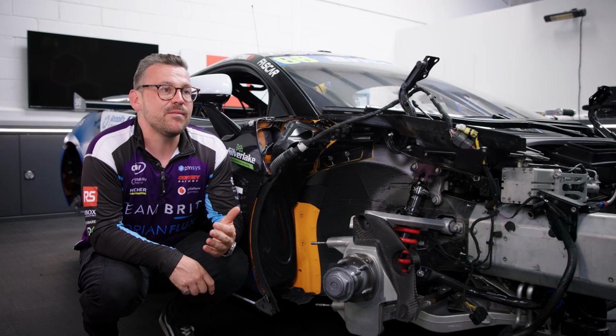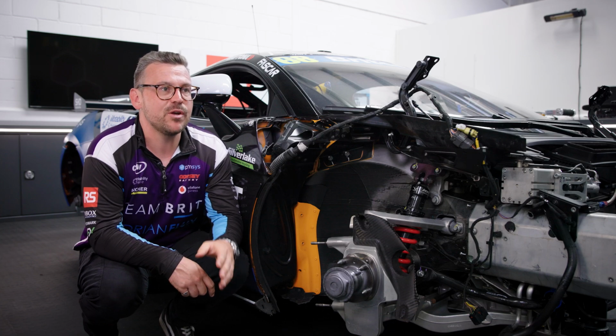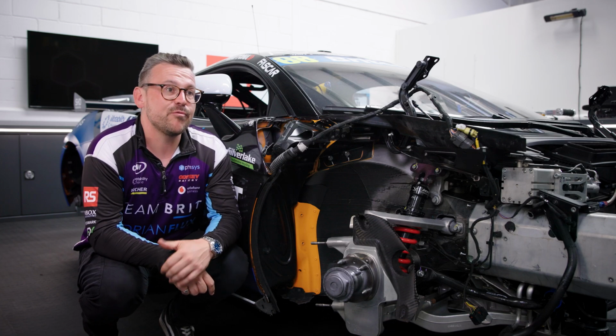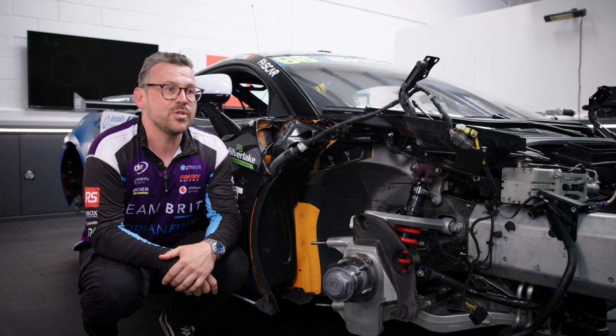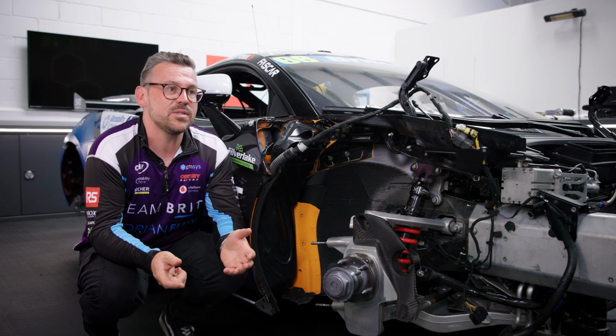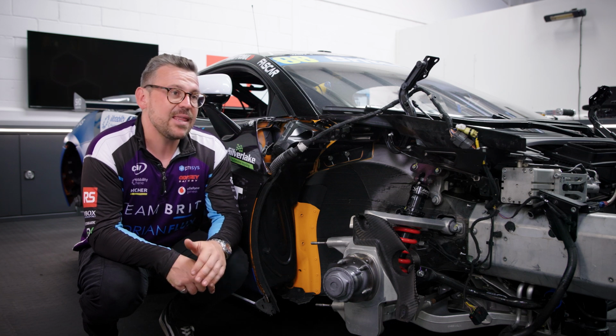When we talk about the vehicle dynamics metrics that we really want to measure, the key things for us are the 7 rotations. Those are the 3 rotations around the X, Y and Z axis, which are pitch, roll and yaw, but also the rotations of each of the 4 corners, so each of the 4 wheels. With that in mind, one of the key things to measure with sensor data on a car is wheel speed.